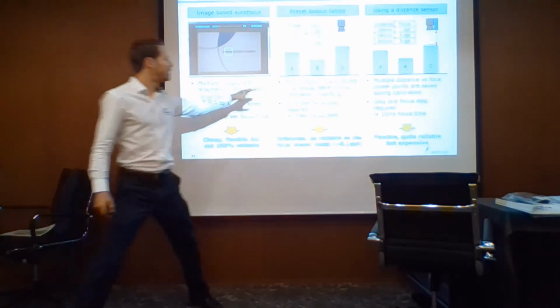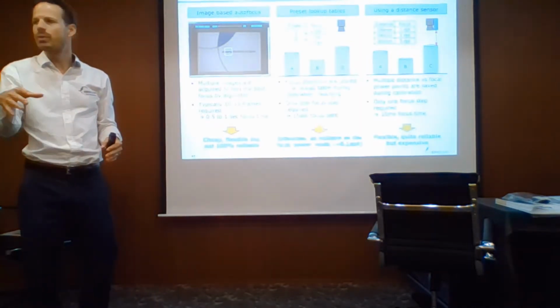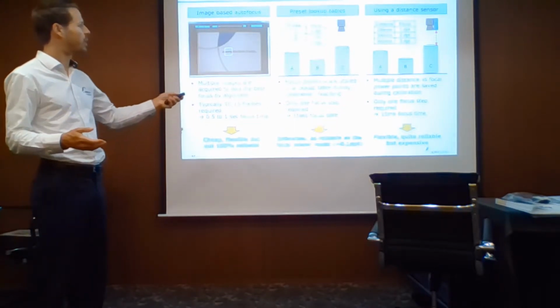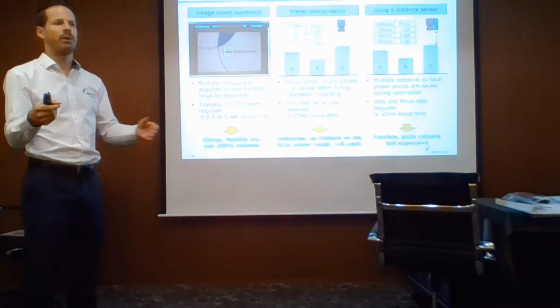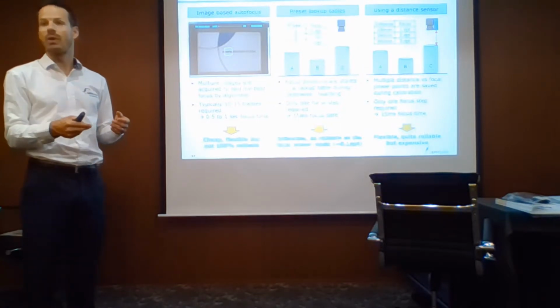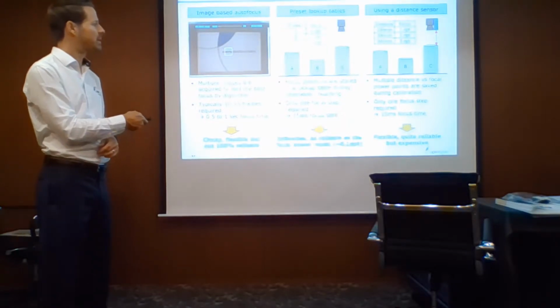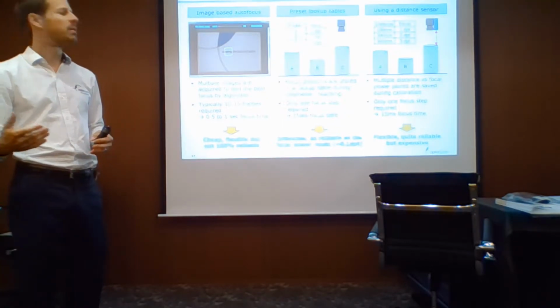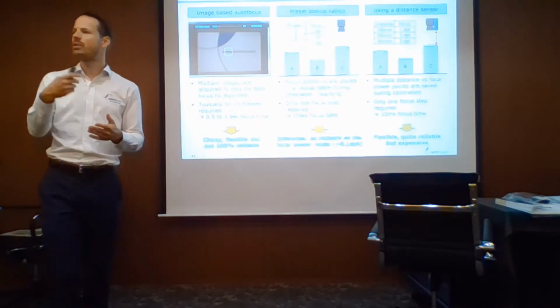Basically, there are maybe 3 products, A, B, and C, and the PLC system or the computer knows which product is coming, and then there's a very simple lookup: for product A, maybe 2 diopters, for product B, maybe 1 diopter. So you just choose the right diopter setting because you know what's coming. This has to be pre-programmed. Typically, this lookup table is in the software or in the PLC that runs the machine. And the benefit is a very fast focus time, so only one jump is needed.